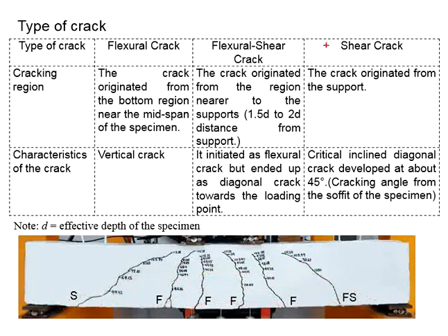The third type of crack is the shear crack. This kind of crack normally happens near the support. It is typically an inclined crack, and normally it happens rather fast. The beam with flexural crack more dominant will have a more ductile failure. Meanwhile, the beam that fails with the shear crack normally fails suddenly. This shear crack here doesn't necessarily always start from the soffit. Sometimes it can start somewhere here due to the diagonal tension of the member.